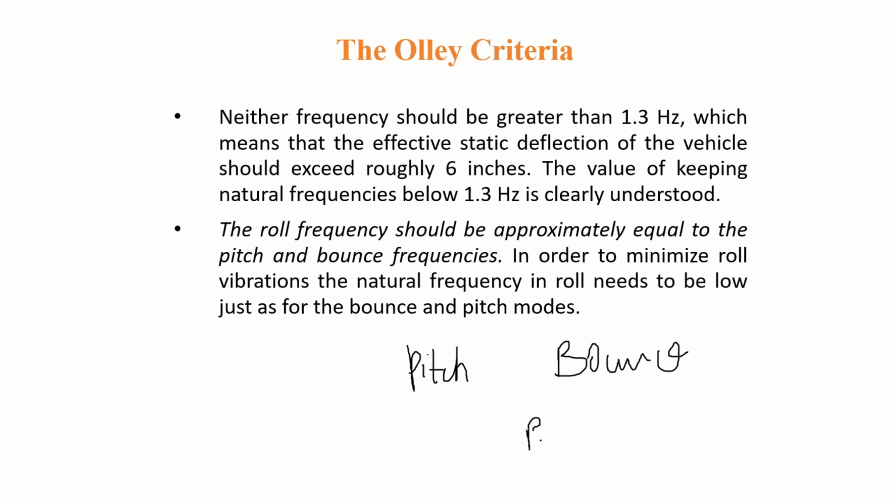Of course, there is roll frequency also. Neither the pitch frequency nor the bounce frequency should be greater than 1.3 hertz. That's very important.